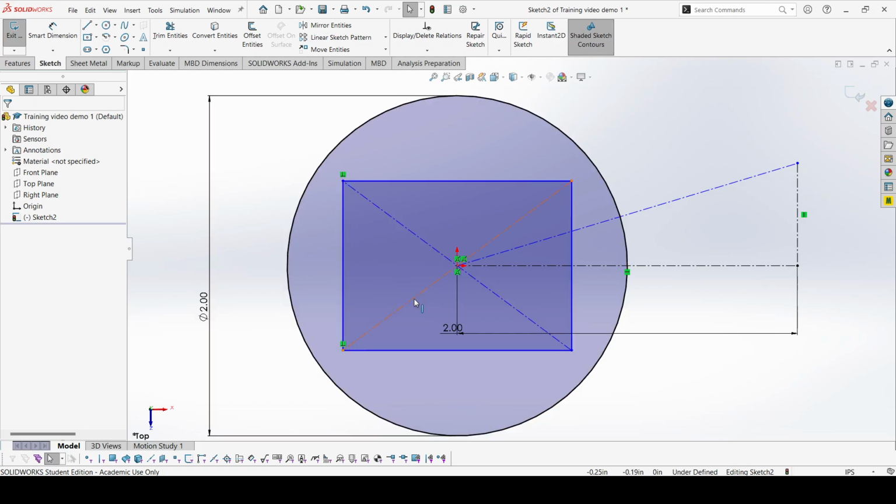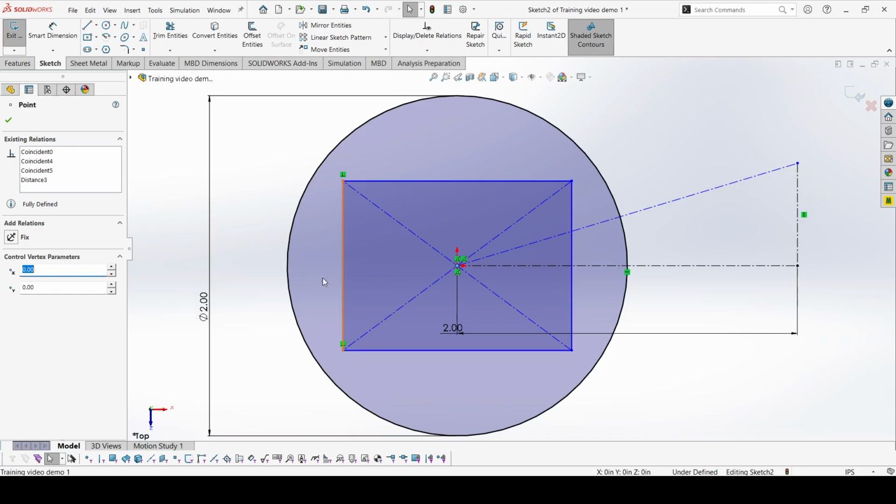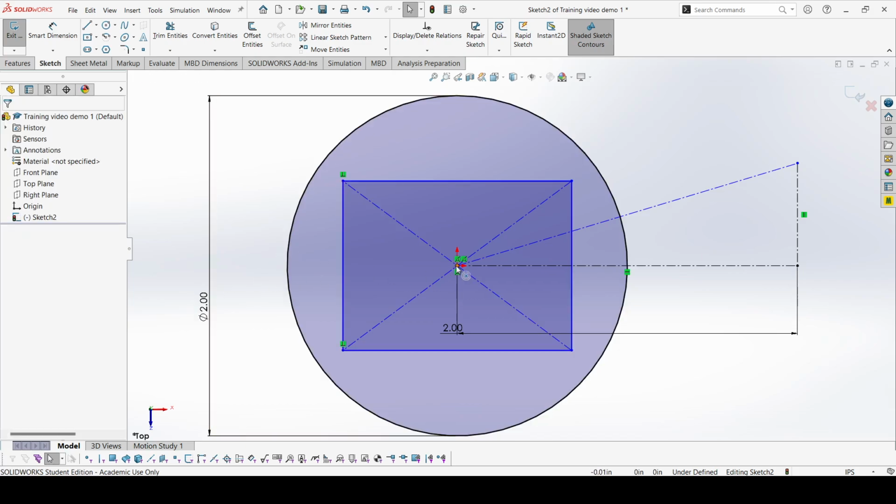Now, actually, it's really cool. You'll notice this little thing that looks like a T intersection right here. This is coincident. This is actually a really cool thing. If something is coincident, that means they connect, or if you were to extend them indefinitely, they would collide. What this is saying right now is that the midpoint of this is coincident to that point. Alternatively, I could have made the origin, actually I couldn't have, because you can't make the origin the midpoint of something, and you can't merge the origin into a point. You can only make them coincident. So that's actually why these are coincident.